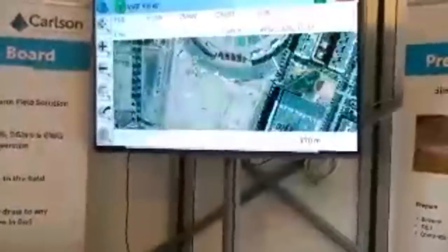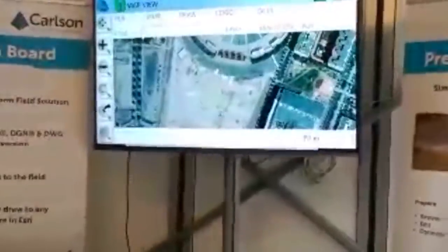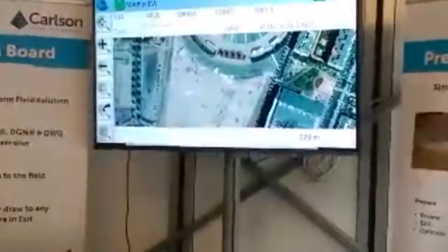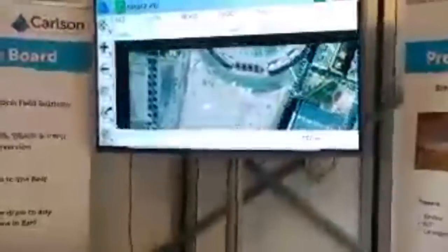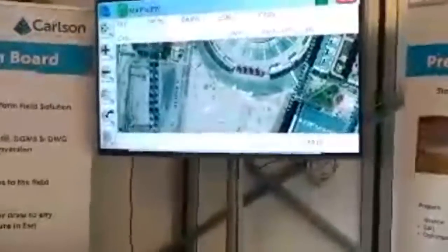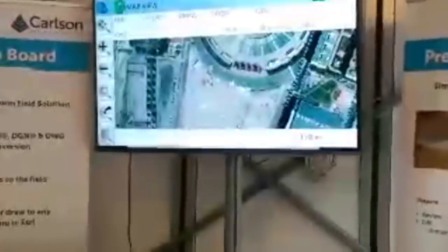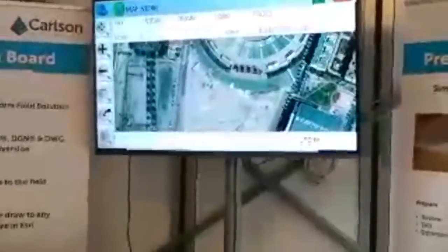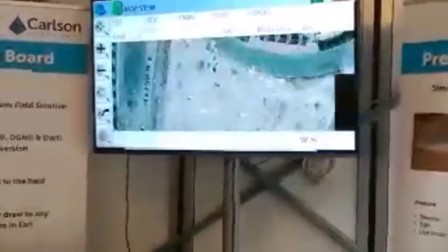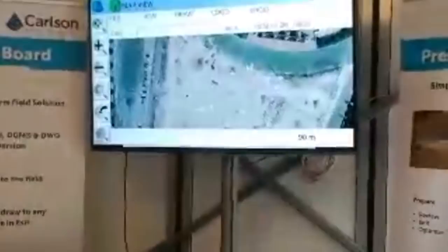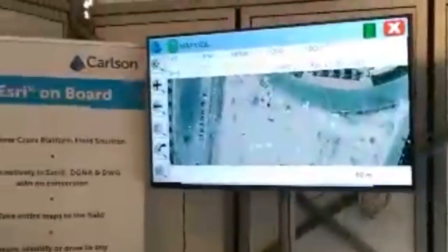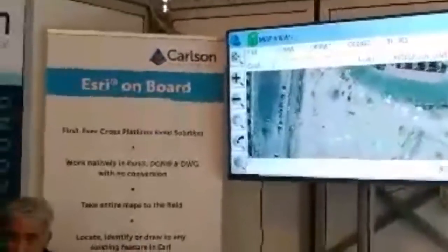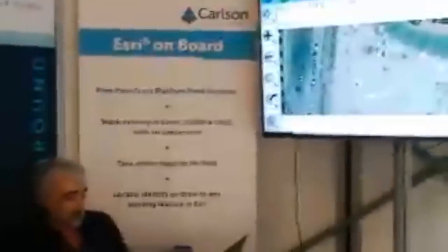The circle is 50 meters radius, right? We could only do half a circle, 4 points per section, because there were tracks and kiosks and things around. But we did this in the range of 40 something meters, with 4 points. 25 is the occupation point, so this is the station point for the robotic. So 21, 22, 23, 24 were taken with hybrid, GPS and robotic, same shot.